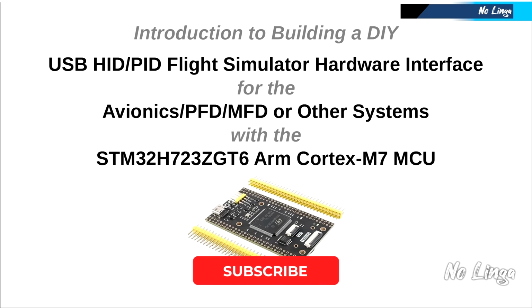If you're not familiar with HID or PID, HID is a human interface device, and it allows you to connect to your PC or computer, and it automatically maps certain functionality for buttons in a flight controller or a joystick without having to install drivers. Similarly, the PID is a physical interface device that allows you to do the same thing by getting information back from a flight simulator, like force feedback from the cockpit in a flight simulator.